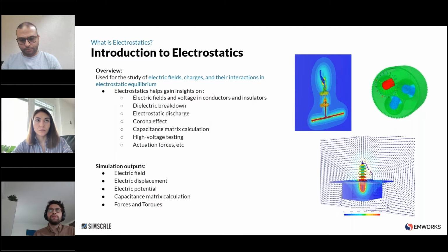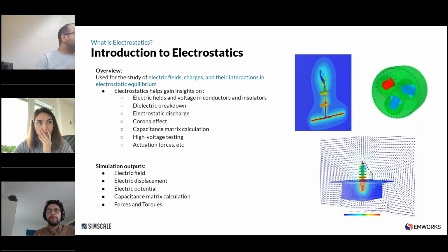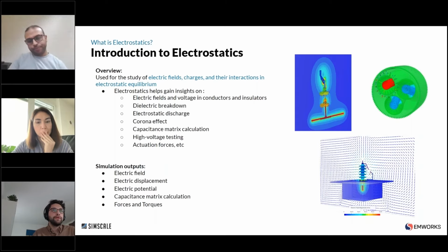The simulation outputs from an electrostatic simulation, of course, relate quite well with the insights that we can gain. We can obtain information on the electric field, the electric displacement, the electric potential. Very important as well is the capacitance matrix and forces and torques.